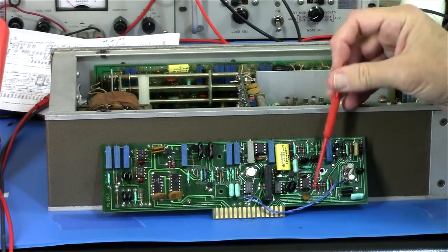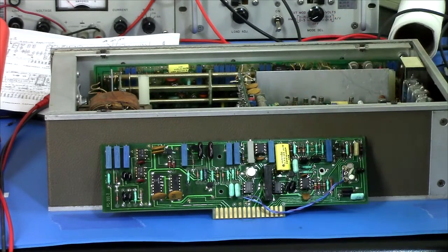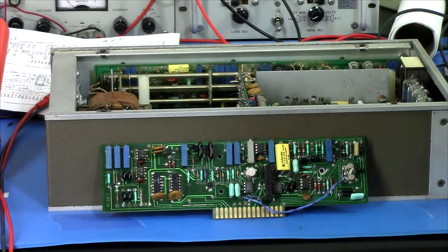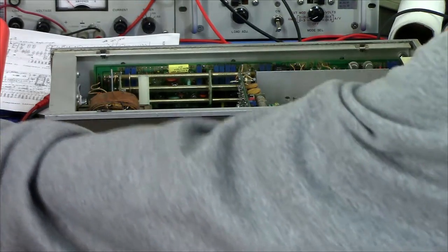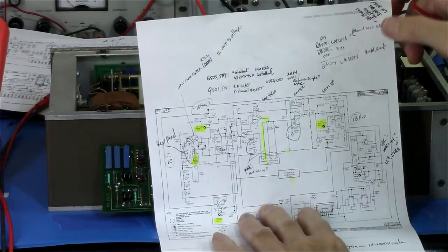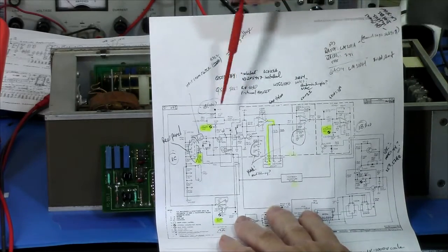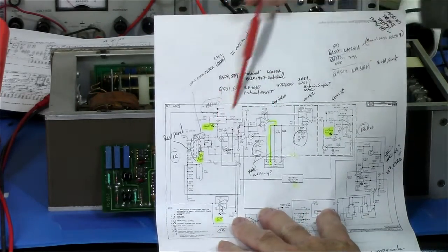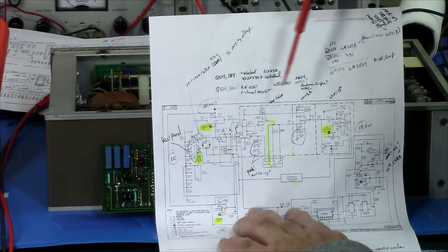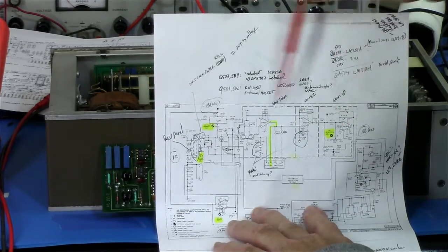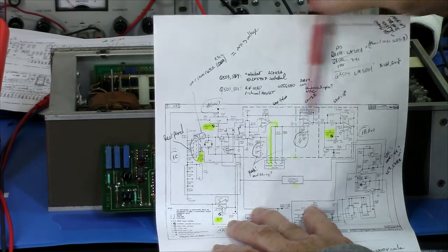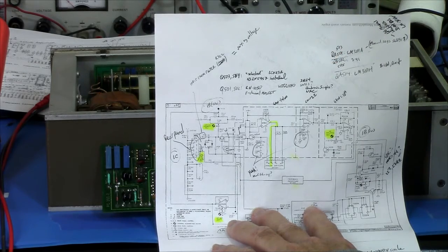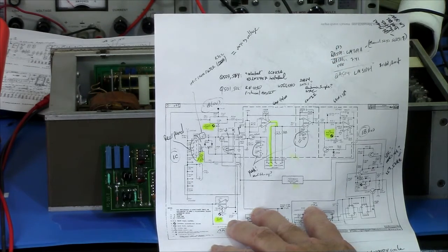Well, okay, so with new chips swapped in, it doesn't change the behavior. Fine. It's not those. Over here's a resistor. I've lifted the leg. So, what's going on here? We have this circuit, and there's like 3 op amps here, and those are the ones that are now socketed that I have tried replacing, just because I suspected them, and for other reasons.